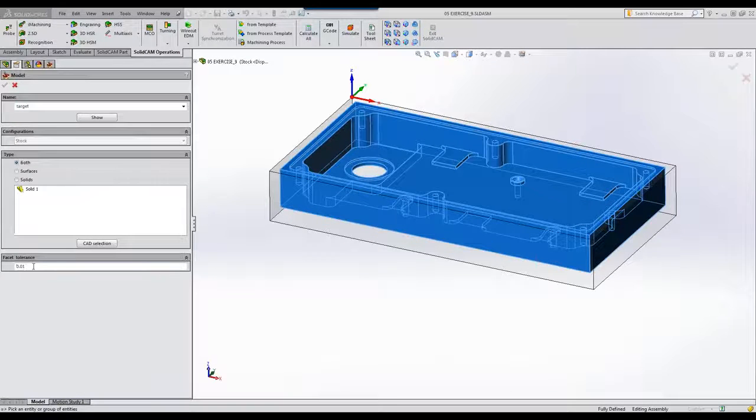we have here something called facet tolerance. Keep your facet tolerances tight. Okay? What's recommended is 0.01 millimeters.